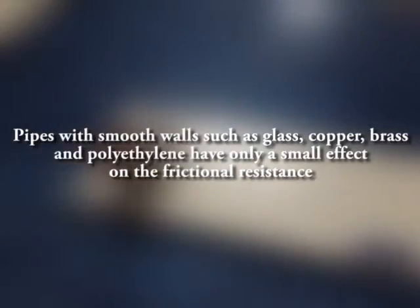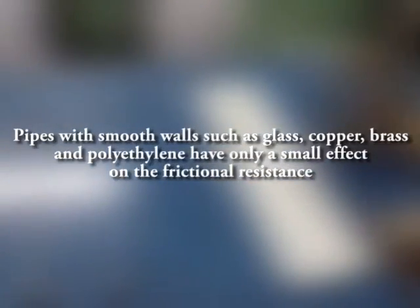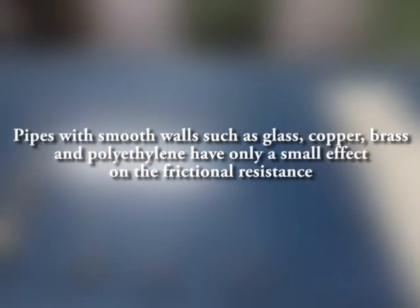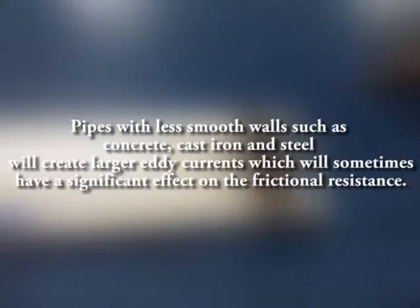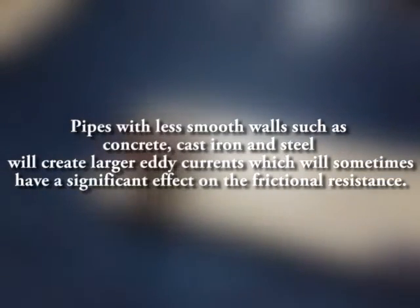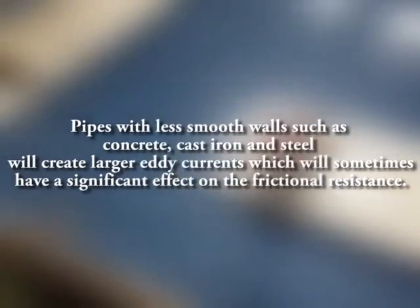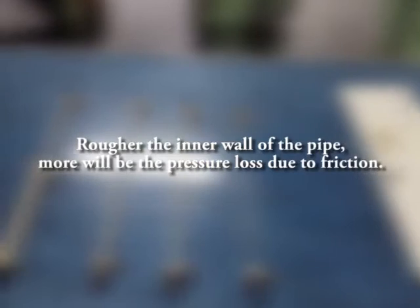Pipes with smooth walls such as glass, copper, brass, and polystyrene have only a small effect on the frictional resistance. Pipes with less smooth walls such as concrete, cast iron, and steel will create larger eddy currents which will sometimes have a significant effect on the frictional resistance. The rougher the inner wall of the pipe, the more the pressure drop due to friction.